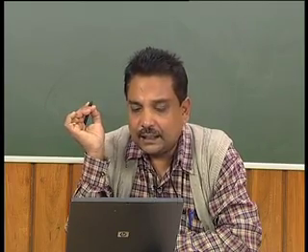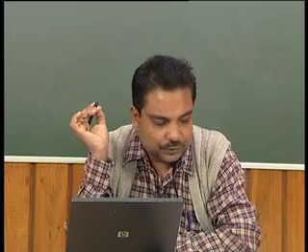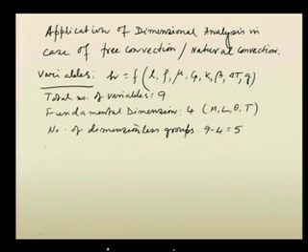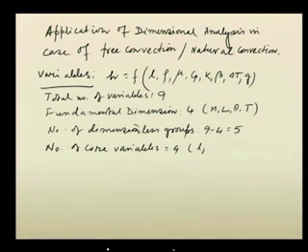Anyway, we have now seen that a system of natural convection or free convection could be defined by 5 dimensionless groups. So, we have to choose the 5 core variables. The total number of variables we have is 9, and 5 will be the dimensionless groups. So, the number of core variables will be 4. Let us assume that the core variables are L, then mu, then k and beta. These are the 4 core variables.